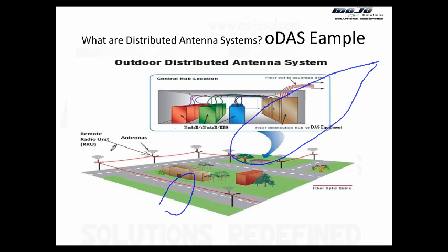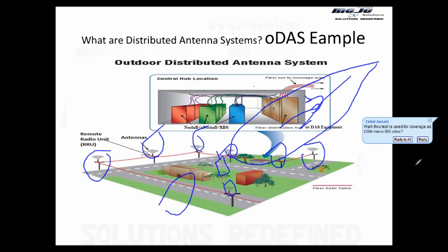But you make sure that these antennas are the dominant server for this UE, because when you plan, you know the coverage of all of these antennas. So you plan those antennas. If the macro signals are coming in, then what is the strength of this macro? You have to plan all this.